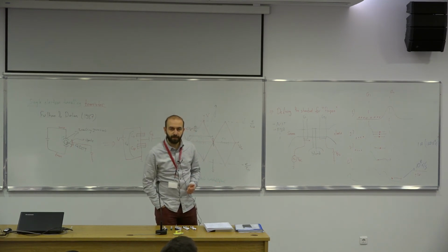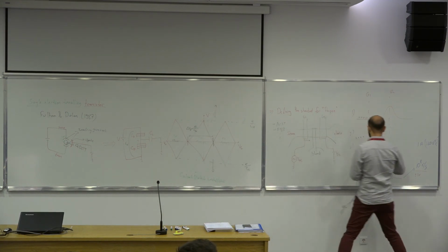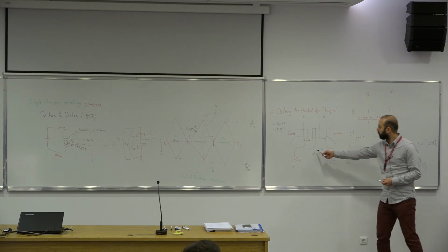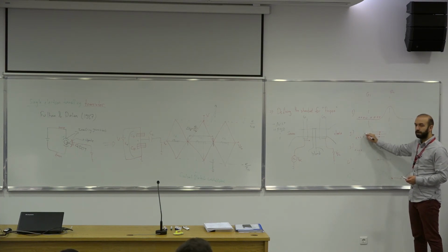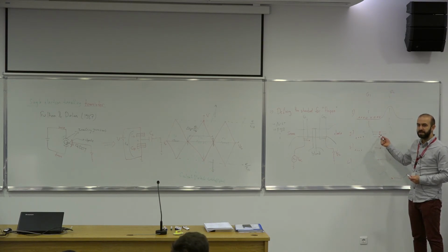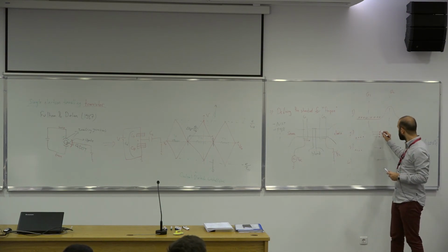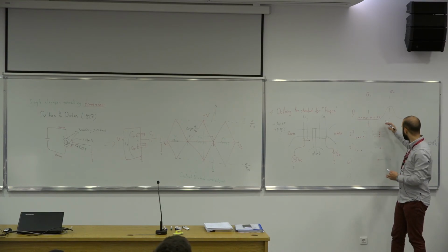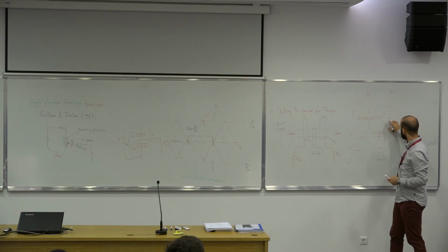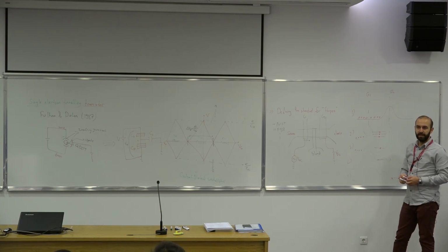Of course, yes? What happens to other electrons in the stage 2? So what you do is you slightly increase the voltage on the island. Okay? So these higher energy levels will go higher, and then they'll tunnel back. And I'll show how this is possible in a minute. Although you apply a source drain bias, actually electrons can go back since the potential here is large enough still. So I mean, I draw them to look like equal, but still you have a larger potential here. So electrons can tunnel back to where they come from.